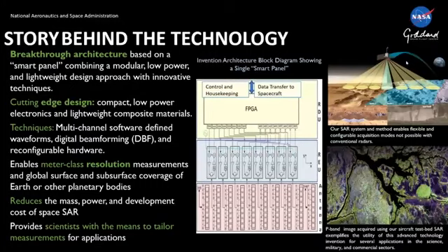So we started out to improve SAR remote sensing by reducing the size, weight, and power of lower frequency radars, and came up with the concept of a so-called smart panel approach using direct beamforming technology as our SAR evolved from a single panel system to an airborne dual panel P-band system that's also interferometric, and to a P-band space qualified system with a number of panels, if you wish.